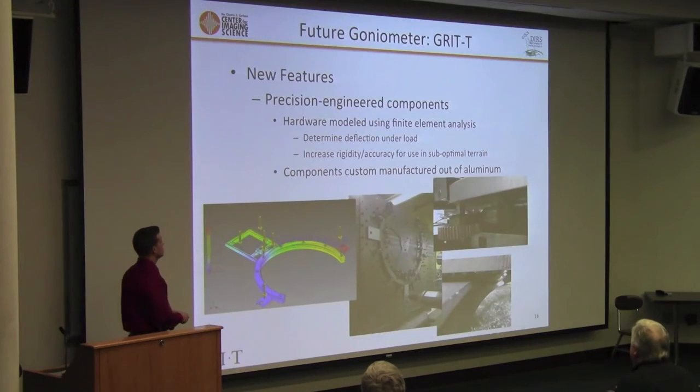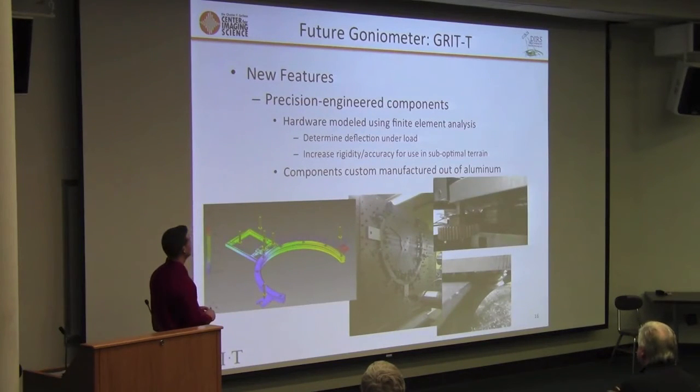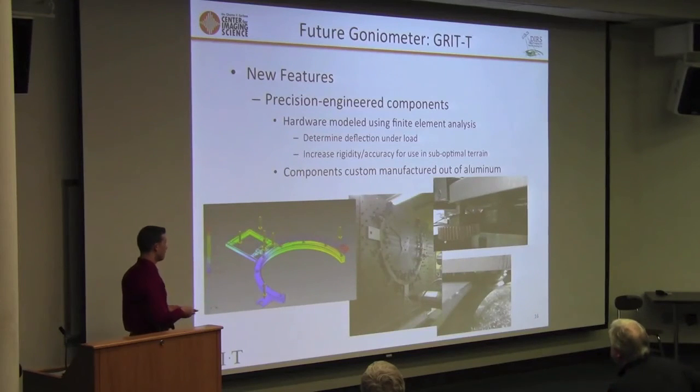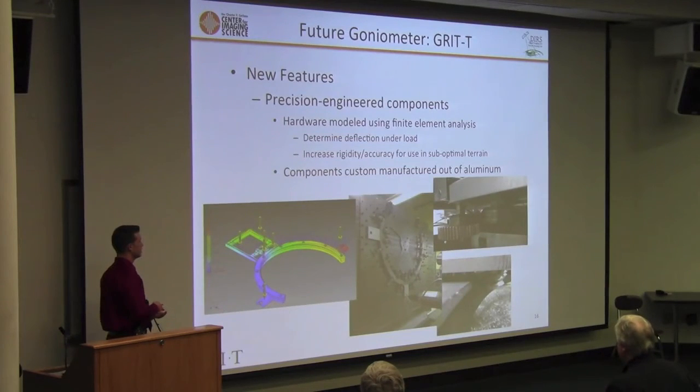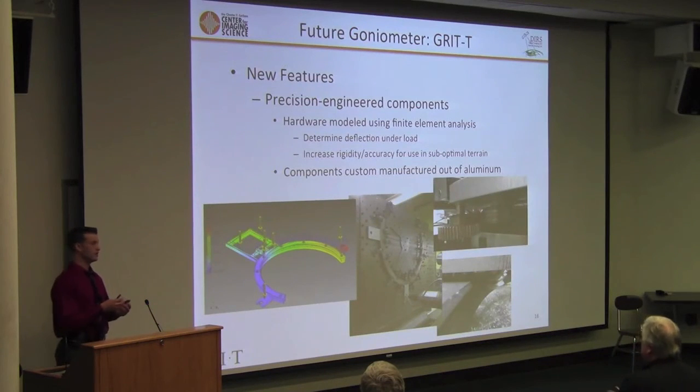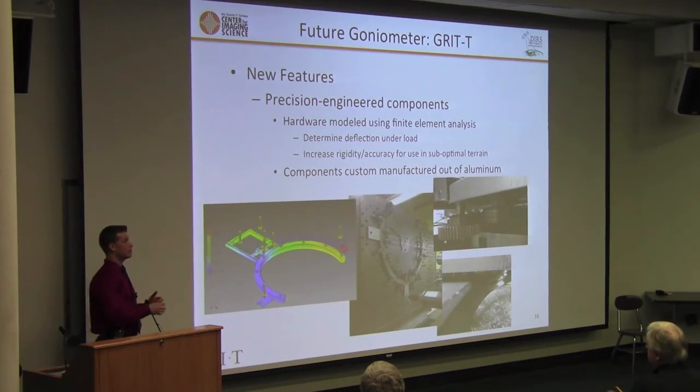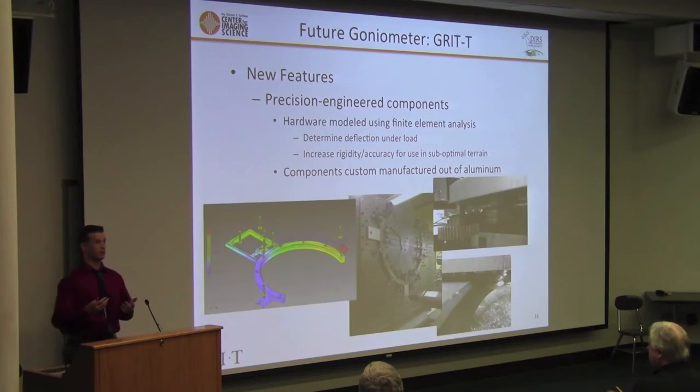So in order to do this, it's been pretty difficult, but we've basically gone to precision engineered components. Everything we've done from a custom standpoint has been modeled using finite element analysis. So not only are we careful of our choice of motors and encoders, to make sure they're sealed and going to operate in all conditions, we also understand the deflections that we're going to see on the system via this finite element analysis.